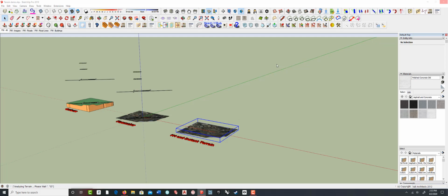By using an image of the site plan, I keep the entire site terrain in one piece. I can mold it, shape it, manipulate it any way I want, but I can still see where the sidewalks are, where the planting beds are, and so forth. So I know where it needs to be level, where it needs to be sloped, and it actually is a really quick way to go through and regrade a site without worrying about where the extra geometry is within the model itself. All right, hopefully it'll finish up here in a couple seconds.